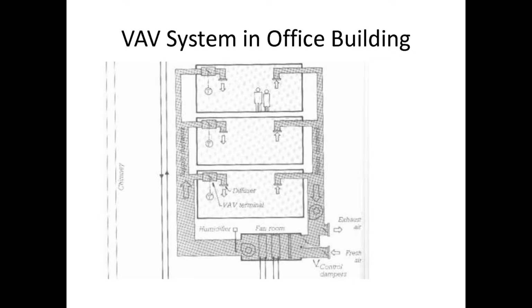Everybody wants a thermostat in their office. Well, that would be pretty expensive to do a tiny heat pump air conditioning system for each office. You'd have 200 condensing units on the roof, and it'd be extremely expensive. This concept is called a VAV system. It gives you as many thermostats as you want.